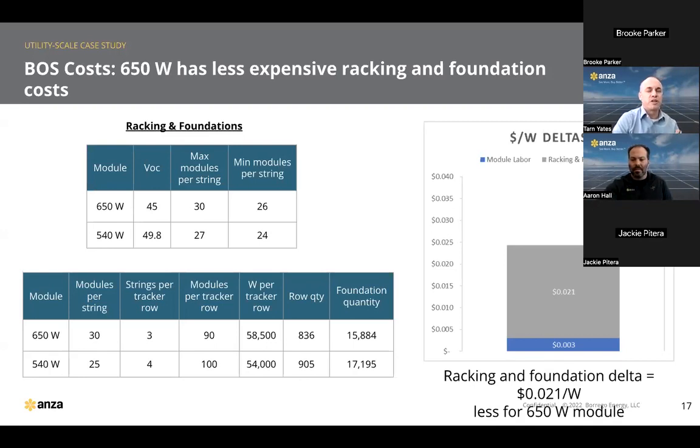And so for this particular racking product, when snow load gets to a certain level, and if you're using a module with a 30 millimeter frame, you actually have to allow for what are called post gaps, which are empty spaces over some of the foundations. And so those post gaps effectively limit the length of the tracker row that you can utilize for installing modules. And it turned out that 100 modules is correct in this case.